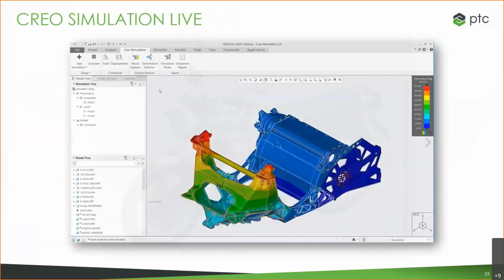And then our last one is our Creo Simulation Live. So this was new to Creo 6 and had a lot of improvements and additions in Creo 7. This is a live simulation tool used as a design guidance tool. So you can have this analysis powered by ANSYS running in the background while you're working. So this is not for the analyst, this is for the design engineer to get some insight while they're making changes to say, hey, if I move this rib over here or move this extrude to the left, what is that going to do to my deformation or to my von Mises stress?